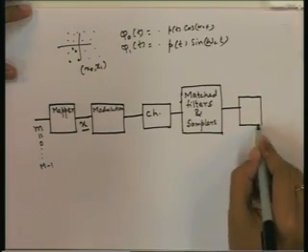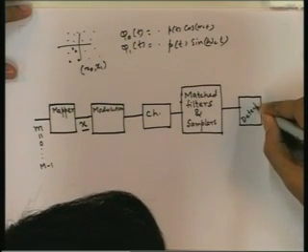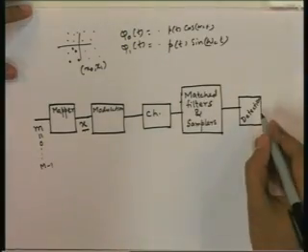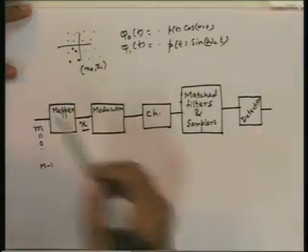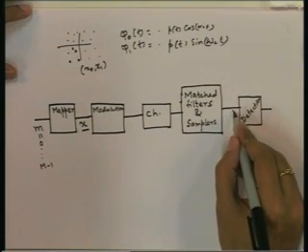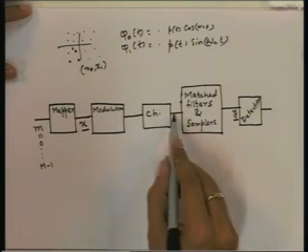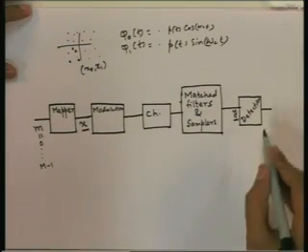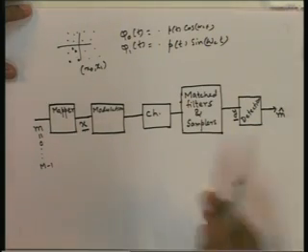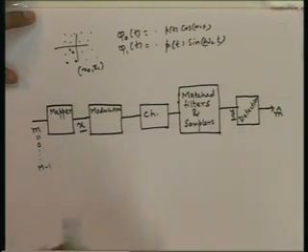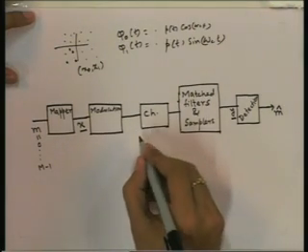We discussed before that this will involve picking up the point from the constellation which is nearest to this vector. So, this is a vector y, this is a vector x, and here the signals are continuous time, here it is discrete time. This will give an estimate of the message m. Now, this is the overall block diagram of the communication system, and this channel is a continuous time channel.